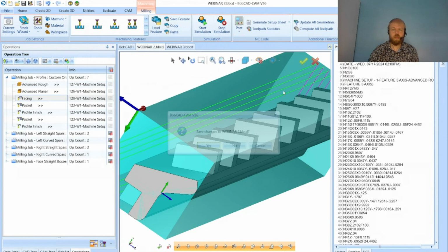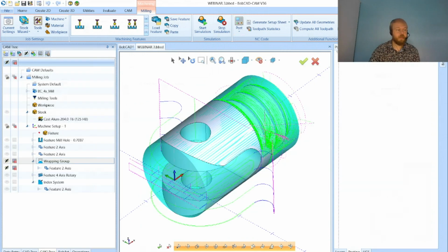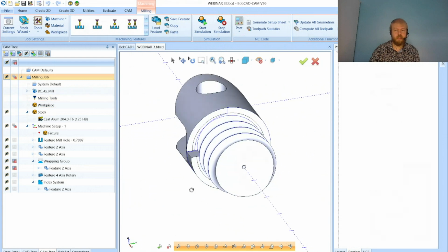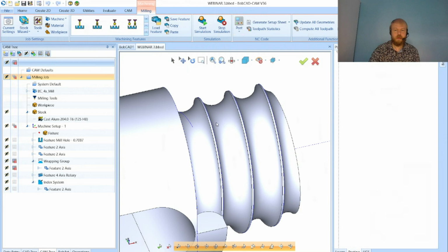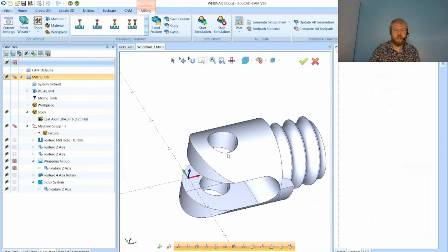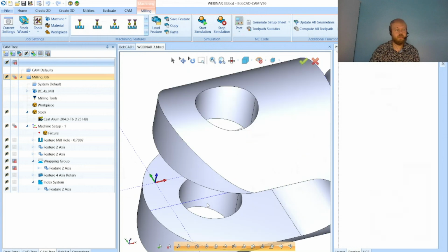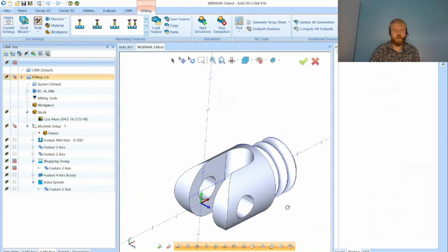So I'm going to close out these two files. We'll get into 3-axis and 4-axis milling in this last part file. Please let me know if you guys have any questions moving forward here. And I'll blank out everything so we can see the part file we're working with here. Basically what I'm focusing on is this thread here and drilling. You might need to pocket this hole, larger hole here, and then profile cutting and pocketing here as well.